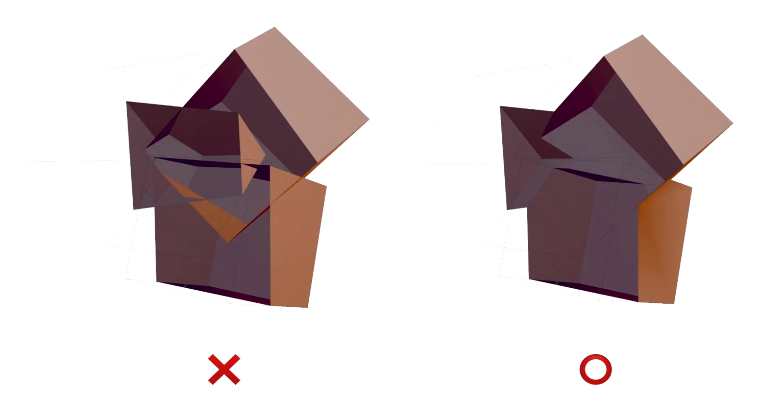If these boxes intersect internally and you try to print the object, the intersecting planes in the internal geometry will cause errors. For 3D printing, the object must meet two key requirements. One is it must be a solid object without internal intersections or self-intersections.